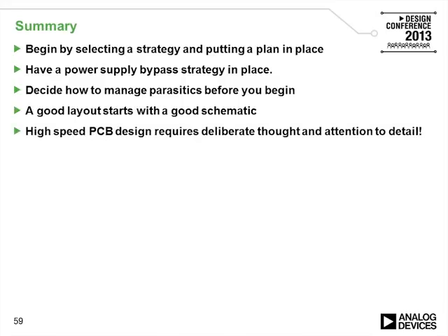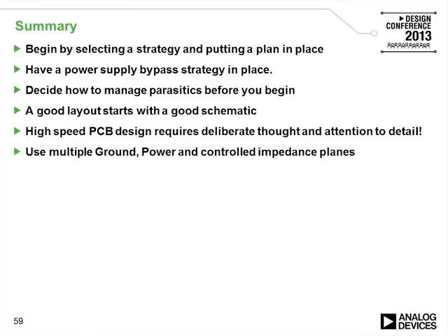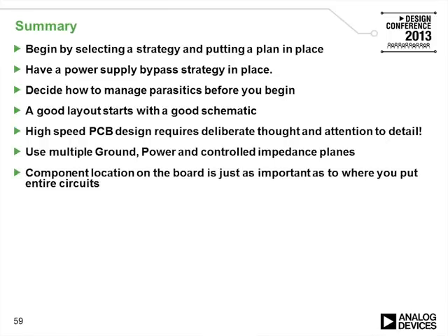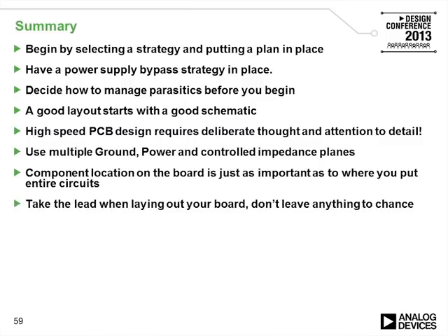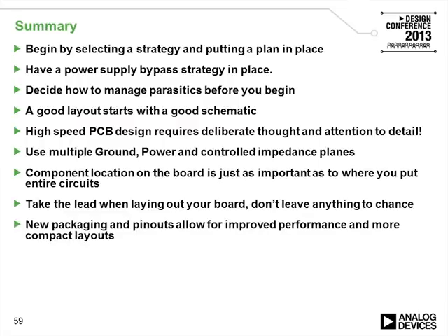Keep in mind that high-speed PCB design requires deliberate thought and attention to detail. Use multiple ground, power, and controlled impedance planes. Component location on the board is just as important as where you put the entire circuits. So pre-plan where the components will be located. Take the lead when laying out the board. Don't leave anything to chance. As a designer, the PC board forms part of the circuit. New packaging and pinouts will allow improved performance.